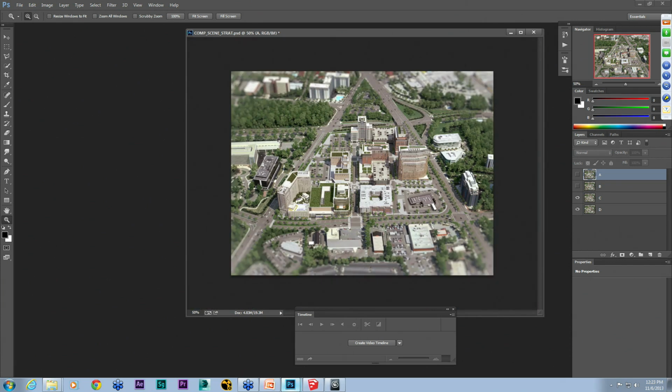And again, we were having trouble with Forest Pack embedded in XREFs through Deadline, with it dropping the Forest Packs at certain frames. One of the things you can do with the power of Forest Pack is actually lay out your forest, and then you can convert it to proxies. So essentially you use Forest Pack as just a scatter mechanism, right? And then embed your proxies.